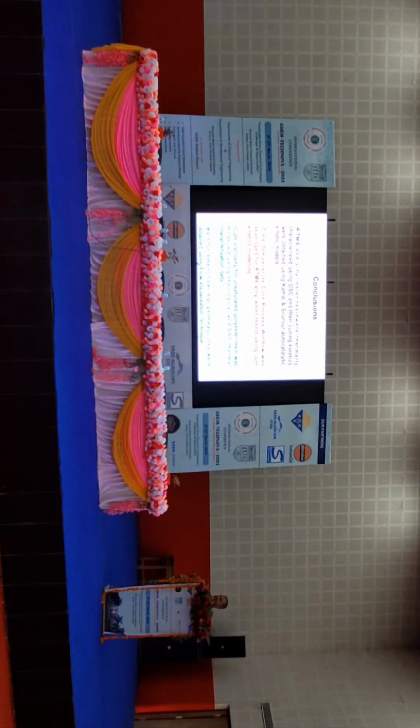From the whole set of slides, we can take home these things. We have developed cure kinetics modeling for RTM6 resin as well as vinyl ester resin, modeled using the Kamal and Sourour autocatalytic kinetic model, and we have developed a time-temperature cure process window for both resins. Cure viscosity also was modeled using rheological and DSC isothermal characterization data. And we understood how to obtain reinforcement mat permeabilities using the flow visualization technique.